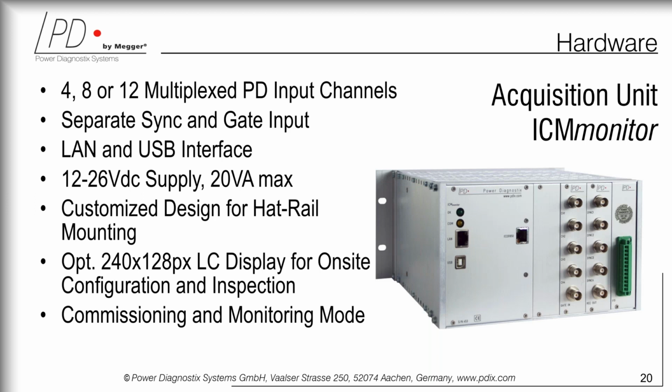Various utilities like to go by the transformer and look at partial discharge patterns. Others prefer to be in the office. Others prefer the substation building. The whole idea here is that signals can come out to say, man, I have a problem. And those come out through the IEC 61850 port, or they can come out through binary relay contact.